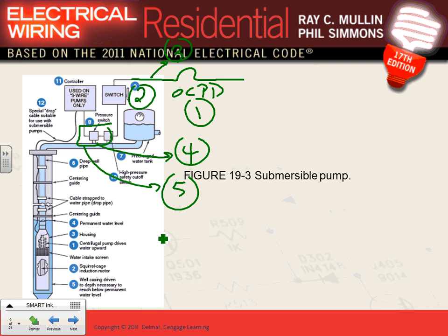Did you guys work with a pressure switch with us in the lab? There's a couple of pressure switches. They open and close based on the pressure. This is normally, what would that be? Normally closed contact, and when the pressure reaches 40, it pushes it to open and it stays open by design until the pressure goes below 20 by design, and then it closes again, and it keeps doing it, right? That's your self-controller.